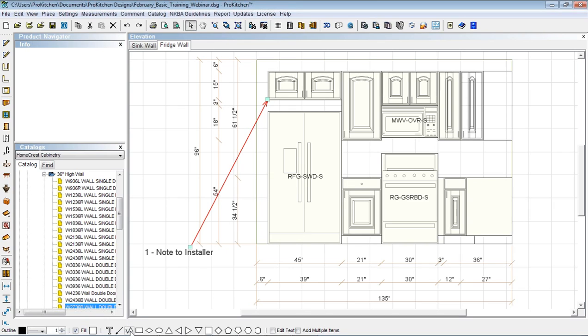And I can come down here and do schematic line. Say I want it to show where the electrical runs. Well, the electrical runs from here, up here, out here, and I know it would never run this way, but it gives you an idea how simple the tool is to work. Every time I left click, I'm doing a turning point, and when I'm done I either hit escape or I can come up here, reset the mouse, click X. Now I'm done with my schematic lines.